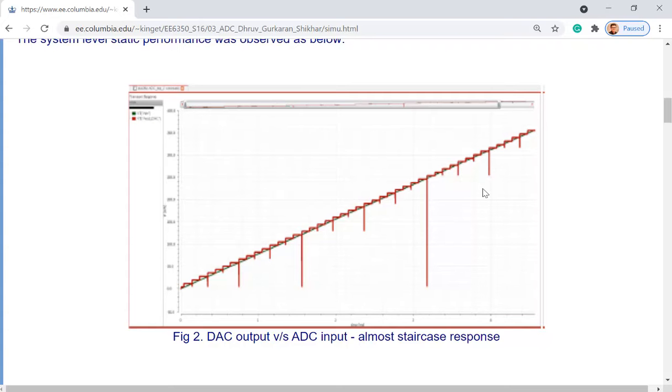And if we use a linear DC sweep, we can feed any possible input voltage to the input of the ADC. You just do a DC sweep. That's the whole range. No other possible input voltages will show up. We already explore all the input voltages.